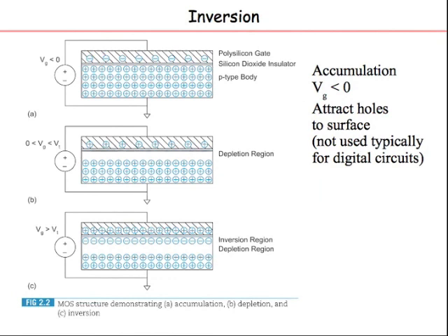One very important concept in MOS technology is this concept of inversion. What we have here is what is called a MOS structure. You have semiconductor, you have oxide insulation, and on top of it is the gate. It used to be a metal gate before, then it became polysilicon material for the gate. Now again people are going back to metal.